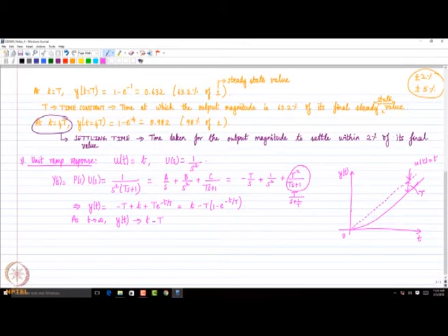Okay, so this is the unit ramp response. Please note that unit ramp is an unbounded signal. Although the system is a stable one, please note BIBO stability means the output should be bounded for all possible bounded inputs. Ramp is not a bounded input. So we should not say, oh, how come the output is going to infinity in magnitude? Yes, it would, because the input is anyway not bounded. The input is going to infinity as time t tends to infinity. That's something which you should keep in mind. So this is the unit ramp response.